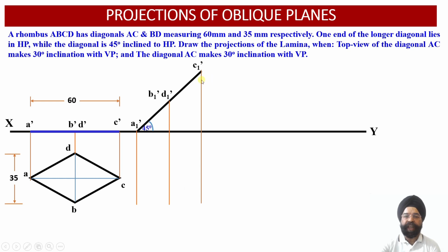So in the corresponding view, what we need to do, we need to draw perpendiculars from this elevation view, and we need to draw the horizontal projectors from the plan projection view which was obtained initially, and work out the corresponding points of intersections of the different point.